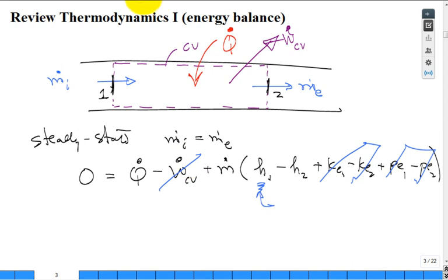So you look at this equation and you rewrite it, and I'm going to switch from Thermo 1 to heat transfer notation. That's why the lowercase q, I made a big deal of this early on in the semester. Lowercase q in this textbook is equivalent to capital Q dot in Thermo 1. They have the same units, it's the same discussion. It is equal to the mass flow rate times H exit minus H inlet. This is a Q into the fluid from the walls of the pipe. It results in an increase in enthalpy.